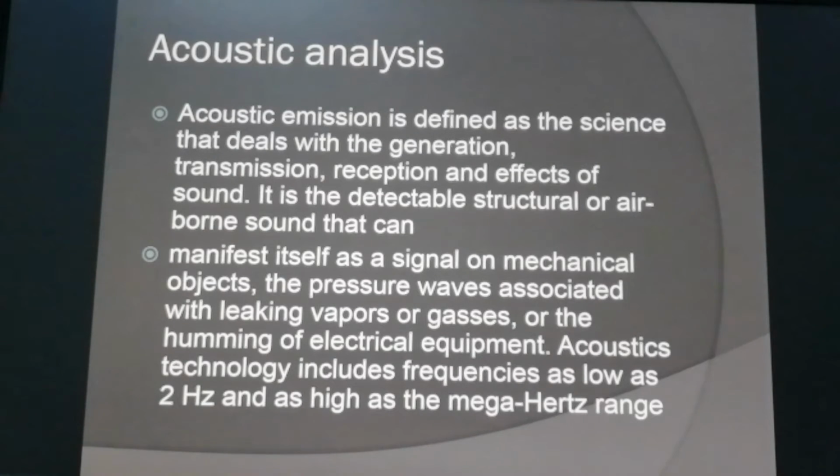Okay, the next one is acoustic analysis. Acoustic emission is defined as the science that deals with the generation, transmission, reception, and effects of sound. It is the detectable structural or airborne sound that can manifest itself as a signal on mechanical objects, the pressure wave associated with leaking vapor or gases, or the humming of electrical equipment. Acoustic technology includes frequencies as low as 2 Hz and as high as the megahertz range.